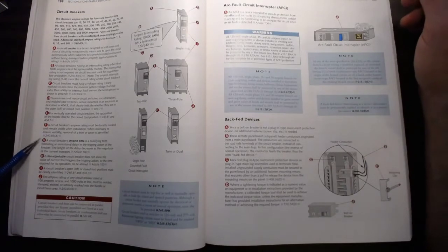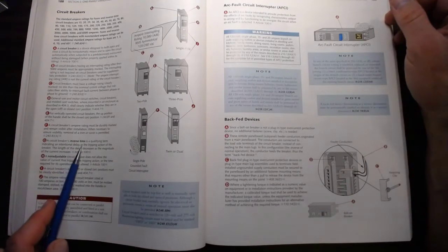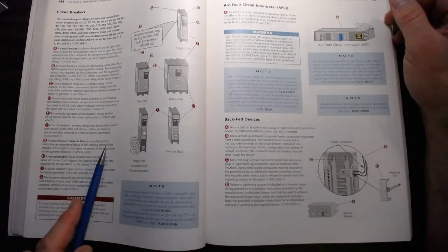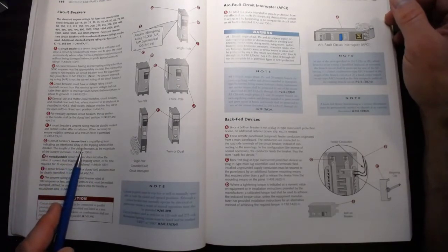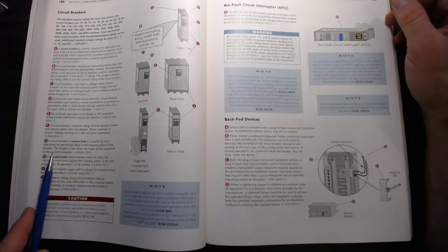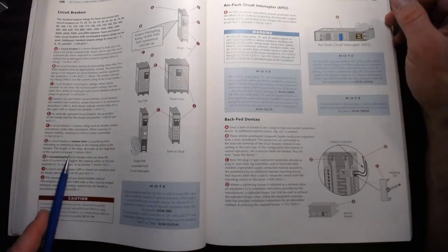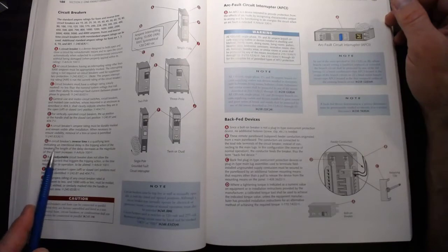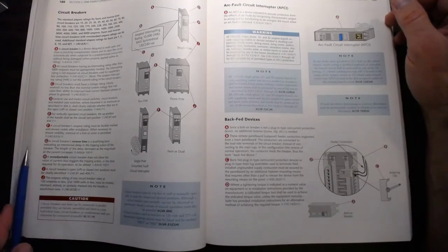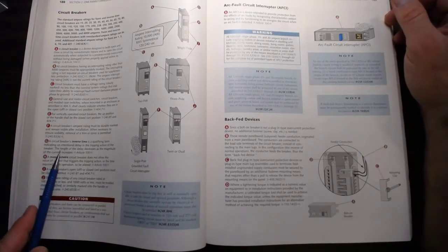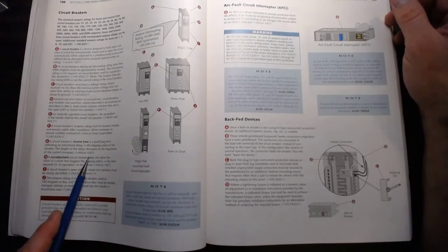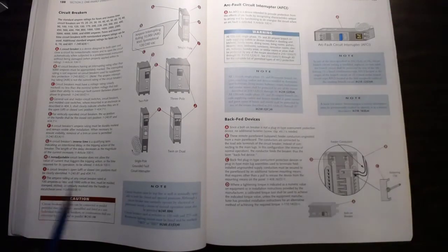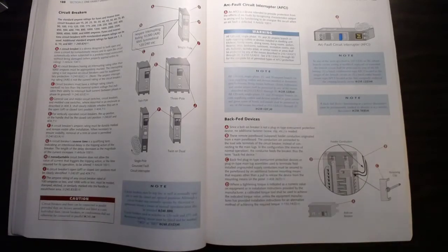When we look at a circuit breaker, we see that a circuit breaker with an inverse time is a qualifying term indicating an intentional delay in the trip action of the breaker. So this inverse time delay means that it will take an overcurrent for a period of time before it opens. It's not instantaneous. So we want to have an inverse time delay when we're starting a motor. We don't want the breaker to trip when the motor is being started and the high inrush current at the very beginning.